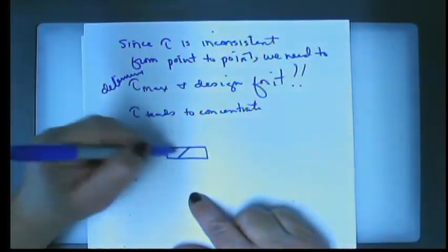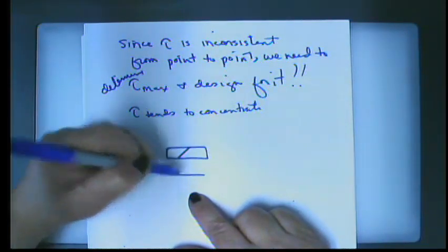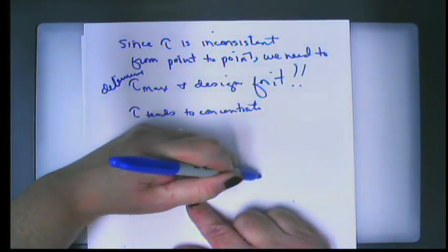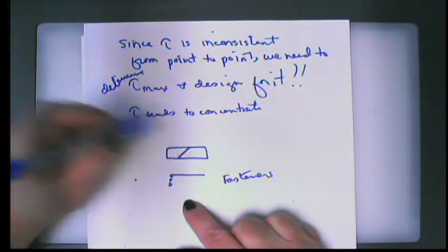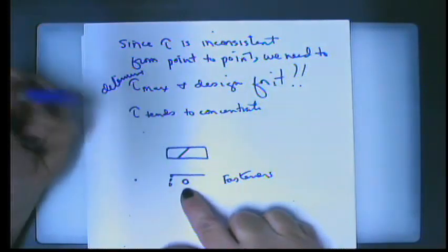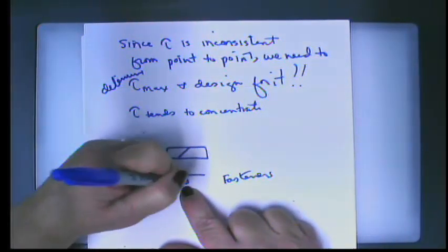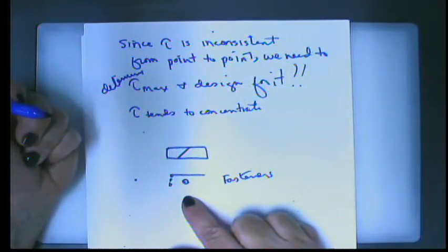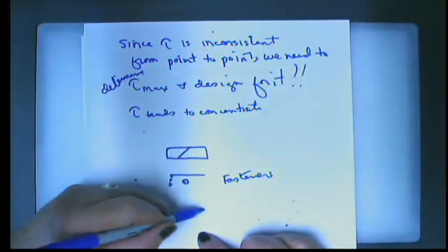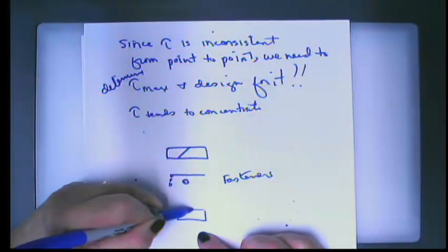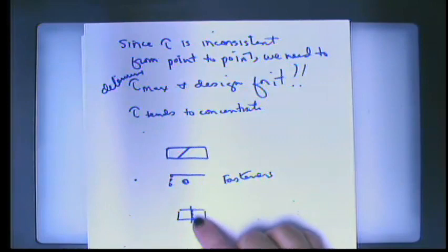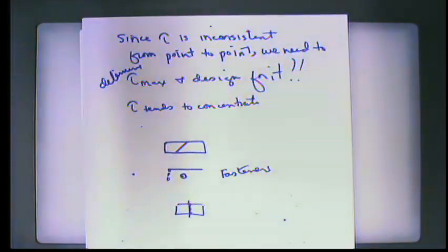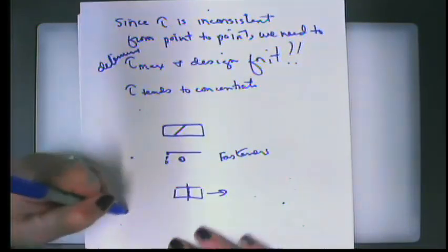But in general, we don't really have glued splices as much as we have fasteners. So what kind of fasteners might we have? Well, you might have a welded surface, which is similar to a glued splice, but often you will have some sort of a fastener, like a screw or a bolt or a nail. If you have a splice here and you have 3 different bolts, all of the tau on that surface is going to be concentrated on those bolts. That's all you have. So that's why they have to be extra strong.